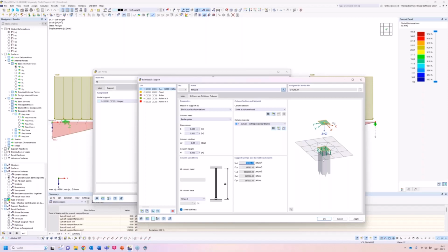Mostly, I think the minimum size would be 18 centimeters by 18 centimeters. For Germany, you almost never go below 22 times 22, I guess. So we can also just take this into account. And the program helps a lot with this. We can just enter our estimated story age. In general, we know it. This is 3 meters right now.